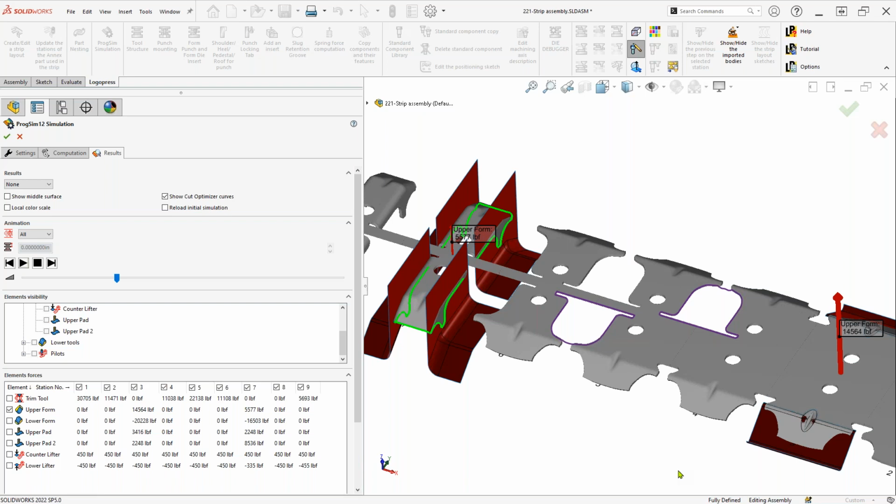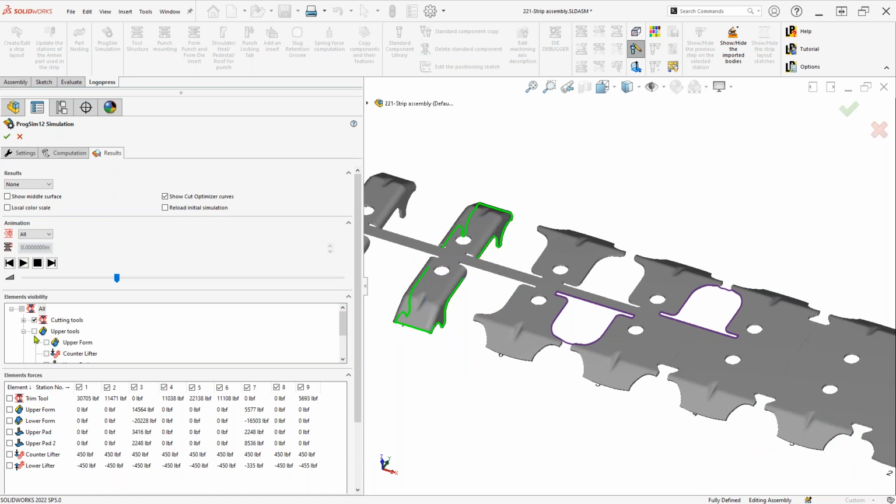It will try to account better for the coining that you get from setting radii and that sort of thing, but it is not going to be something where you could smush an area thinner, like on an electrical contactor or something like that. You're not going to be able to handle that kind of coining operation with this sort of software.